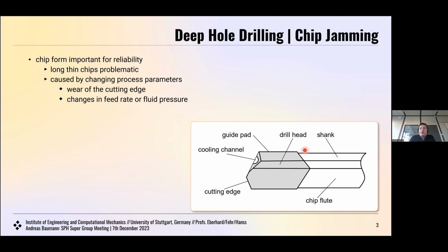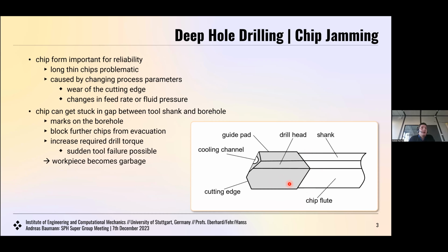First of all, these chips constantly rub over the borehole, leading to wear of the borehole. It can also lead to marks and blocks further chips from their evacuation. It requires an increased drill torque to continue drilling. However, at a certain point, when you can no longer increase the required drill torque, the drill just snaps, because the tool strength is exceeded. And once the drill has snapped, the complete workpiece becomes garbage and you have to start from the beginning.